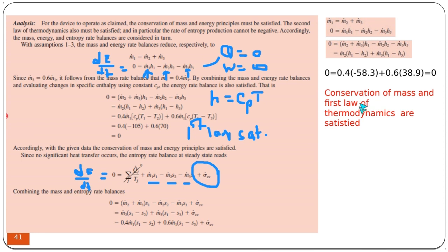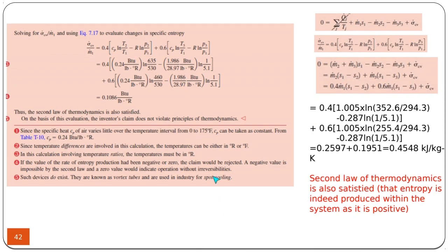So accordingly, when you calculate the entropy balance with the ds equations, remember that this is an ideal gas, so you can use the ds equations for ideal gas. So this is the first term, the second term. Let's take a look at the equation in SI terms. Then you see that the production of the entropy has a positive value.